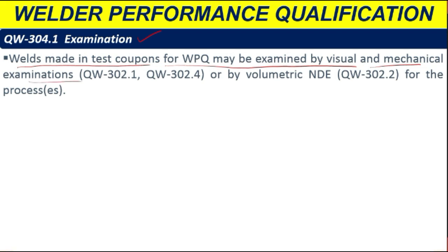QW 302.1 and 302.4 cover the process. So you should always go to QW 302.1 and 302.4 for the visual and mechanical examination, or by volumetric NDE you have to go to 302.2.